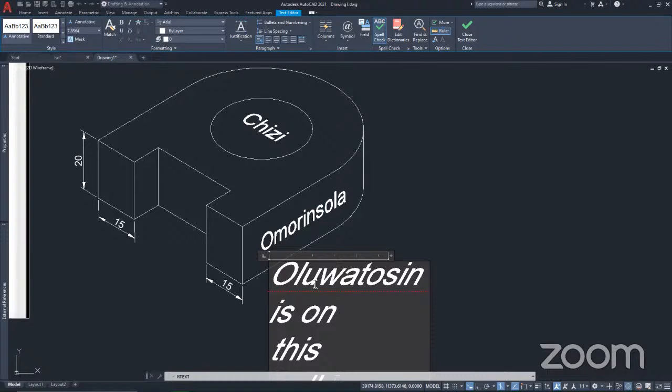Once I'm done and okay with whatever I want here, the text height should also be indicated. Let me use 2.5 as a text height, and say close text editor.